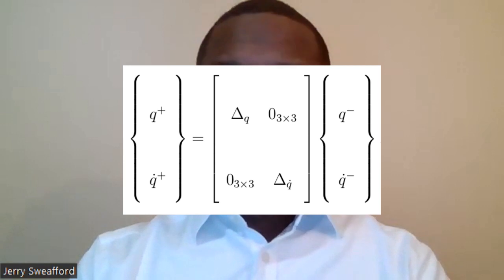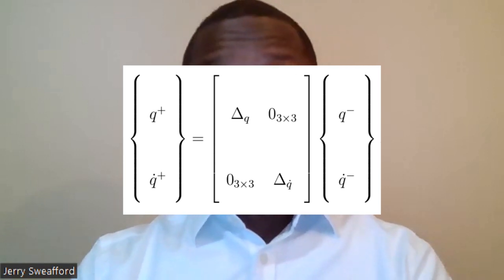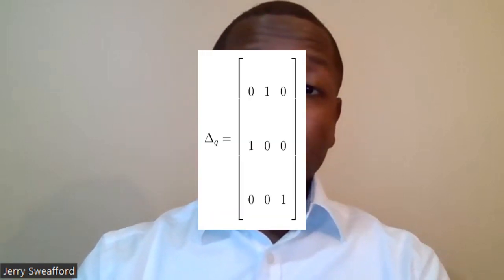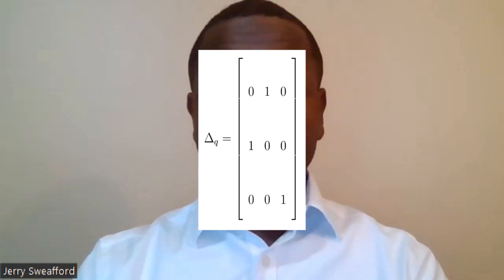As stated earlier, for this robot with point feet, we model each impact as an instantaneous double support phase with a discontinuous state transition. When an impact is detected, a post-impact state is computed from the pre-impact state and supplied as the initial conditions to the swing phase dynamics as a new swing phase commences. We use the following impact model. The plus superscript denotes post-impact and minus denotes pre-impact.